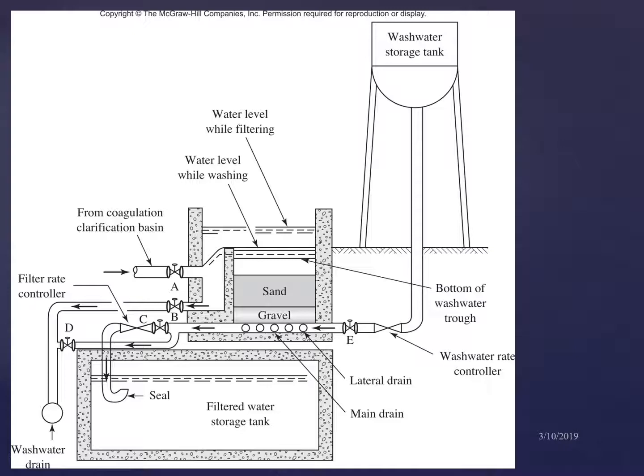And another will be flow rate, what should be in gallons per minute. For example, if you are washing out your filter for half an hour, what should be the flow rate of this tank? And then what should be the height? Based on the height, if you remember, we know what should be the total head. So total head should be static head and dynamic head.